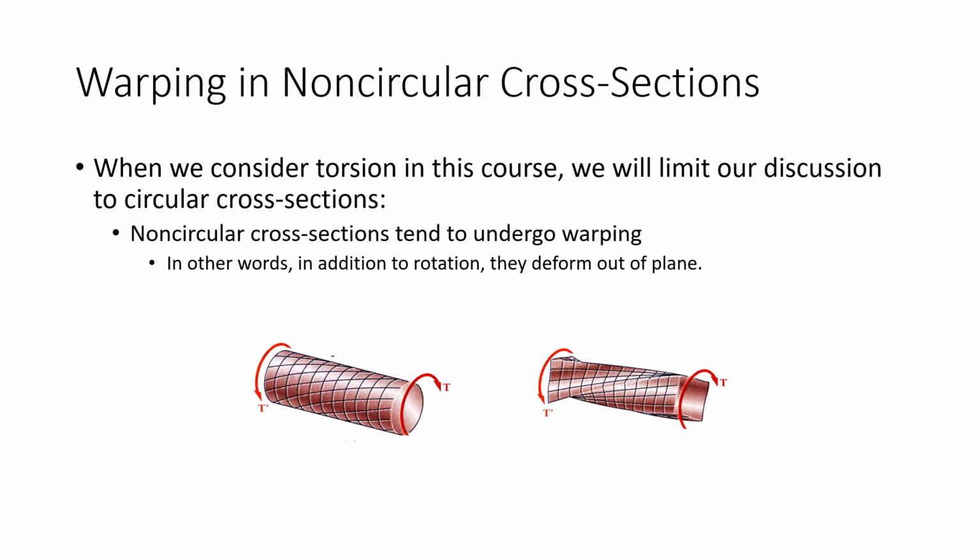So, for example, whenever you have I-beams in buildings, and the I-beam undergoes flexure, the top of the beam is experiencing compression, the bottom of it is experiencing tension. And things in compression, and we're going to talk about this later in the semester, like to buckle. And with I-beams that are being bent, the top wants to buckle, the bottom doesn't. And the beam doesn't really know what to do with that. So when you start getting to that maximum capacity, what happens is the beam sort of kicks out and twists. And there's this mode that we investigate in steel design called lateral torsional buckling. And so there is a twisting phenomenon.